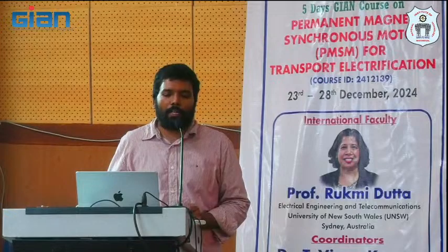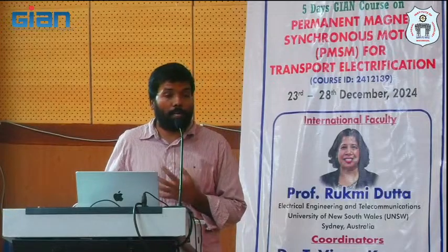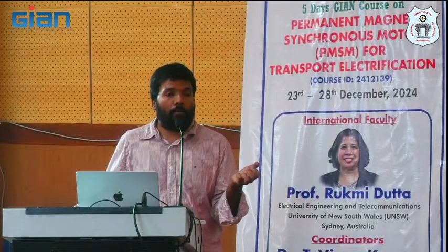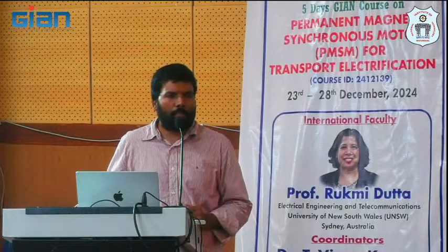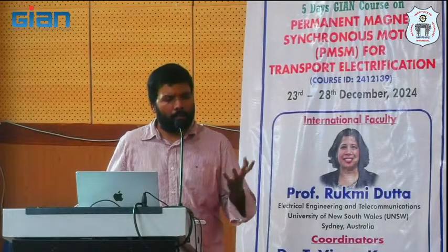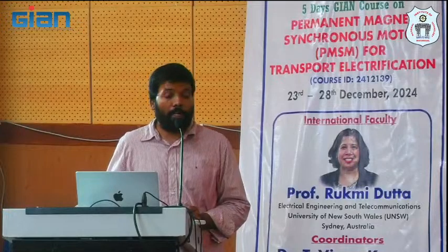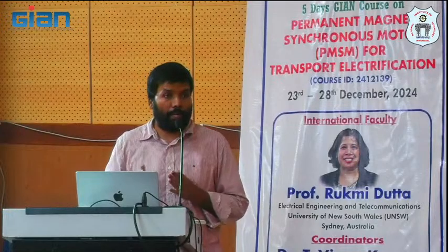Many scholars think that mine is position control, mine is a PMSM, BLDC or SRM machine, so without position, how can we accelerate the machine? Position is not required. Position is required whenever you want to improve the dynamic performance. If you are not so interested in dynamic performance, by using the simple V/f method we can accelerate the machine, but it will take a long time to reach steady state.